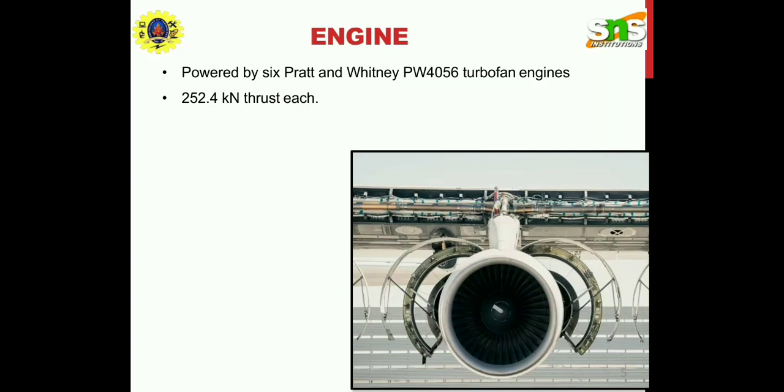In addition, turbo machines can finally be classified by the relative magnitude of the pressure changes that take place across a stage. Impulse turbo machines operate by accelerating and changing the flow direction of fluid through a stationary nozzle. The nozzle serves to change the incoming pressure into velocity. The enthalpy of the fluid decreases as the velocity increases. Pressure and enthalpy drop over the rotor blades is minimal, and velocity will decrease over the rotor. Newton's second law describes the transfer of energy for impulse.